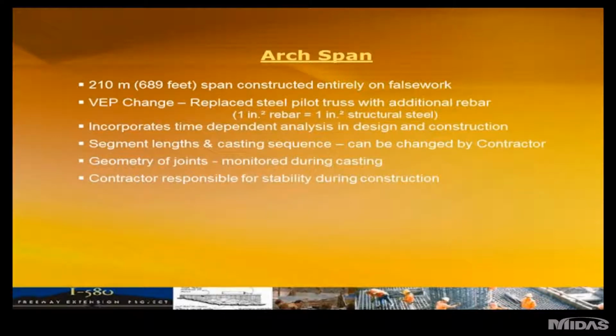Of course, it incorporated the time-dependent analysis for design and construction. The segment lengths and casting sequences were varied from the sequence in the plans by the contractor. Geometry during casting and throughout the entire construction history of the bridge was monitored by the contractor, and the contractor was responsible for stability during construction, as usual.